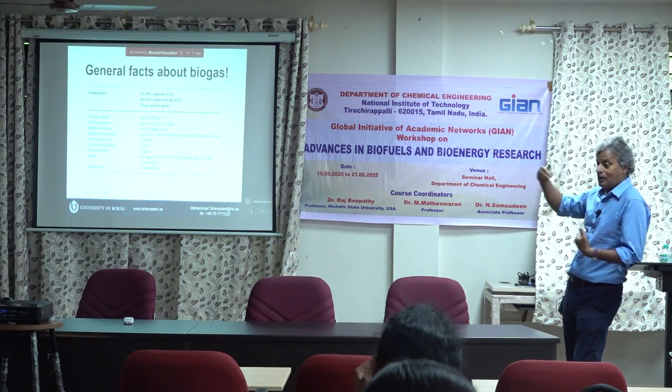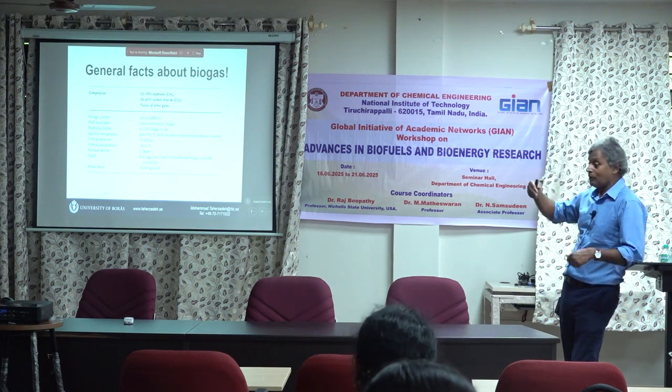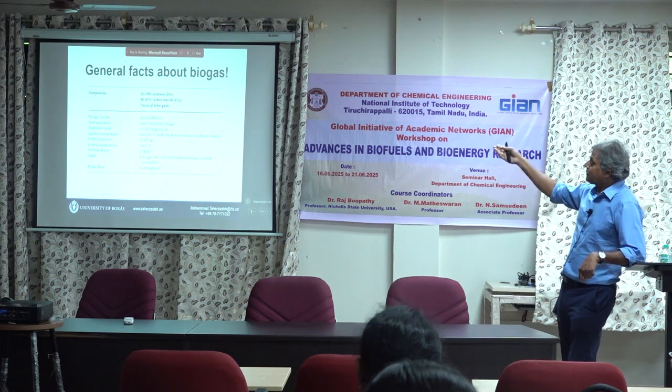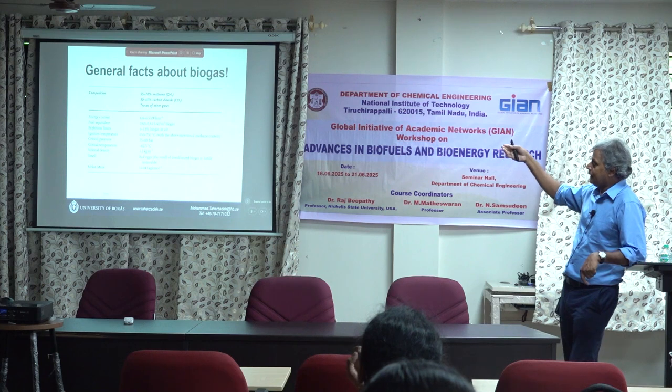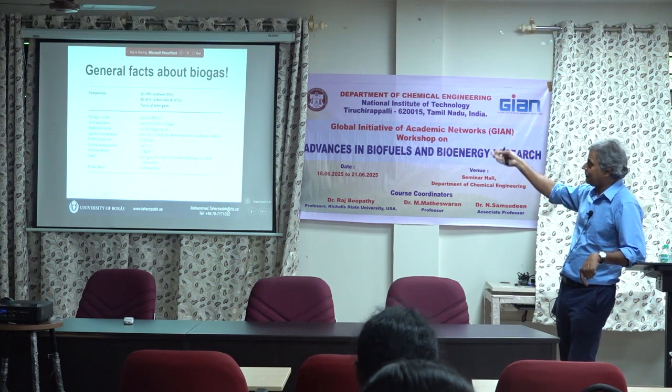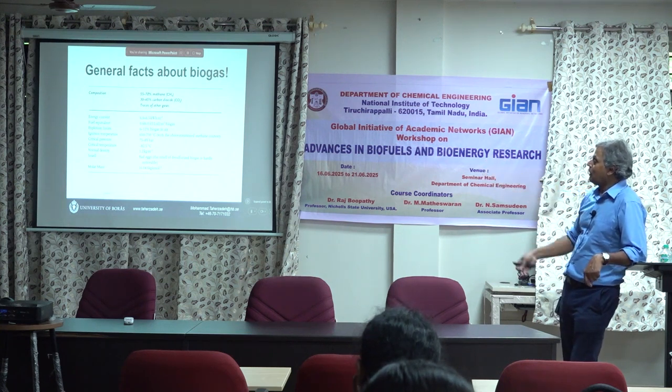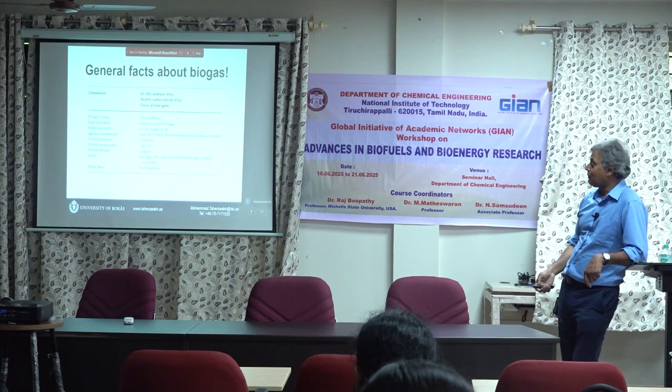You can compare metrics to see how valuable the biogas is. Explosion limits are listed here, along with ignition temperature, critical pressure and critical temperature of methane, and normal density. It also smells: if you have H2S, it smells like a bad rotten egg smell. Methane's molar mass is 16.